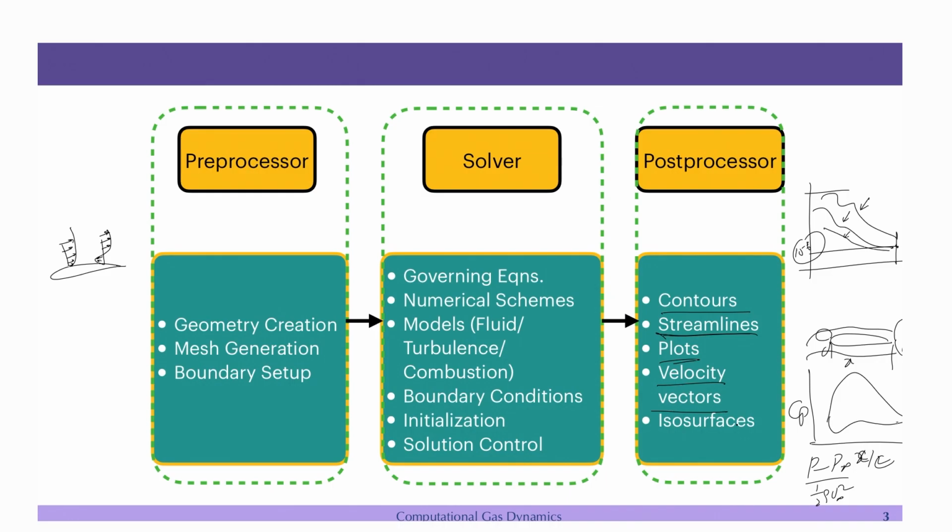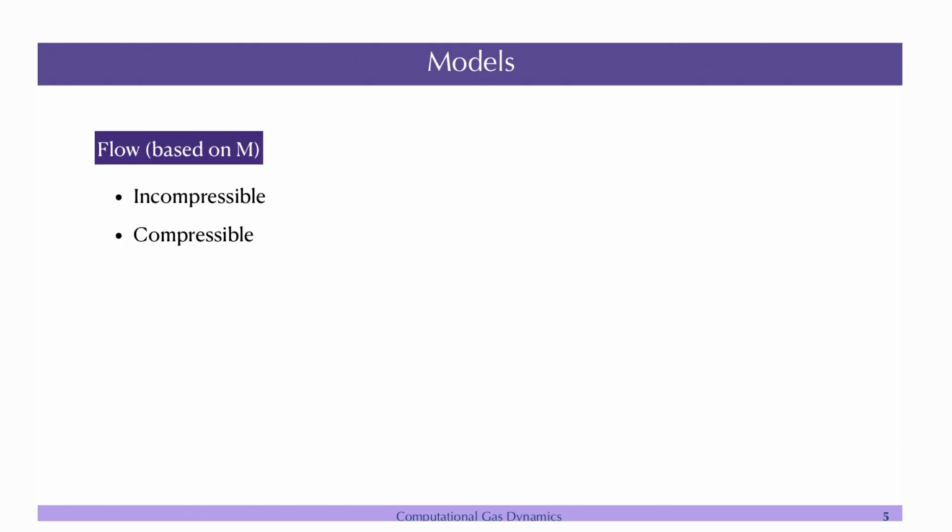Then if it is a 3D flow, for example, you can also have the isosurfaces. You can have isosurfaces of vorticity, or you can have isosurfaces of Q criterion or several other criteria that will give you how the vortical field looks like. Like contour, you can use different isosurfaces of different flow variables that you have, whether the direct flow variable like rho, u, v, p, or you can have the derived flow variable like vorticity, the Q criterion, lambda 2, several other things, any gradient you want to plot, skin friction. So this we have already seen.